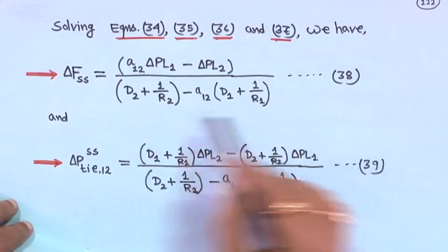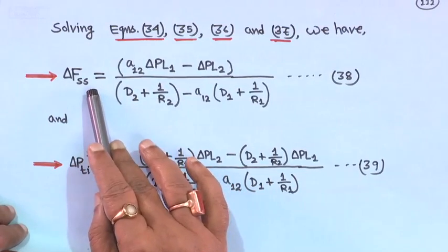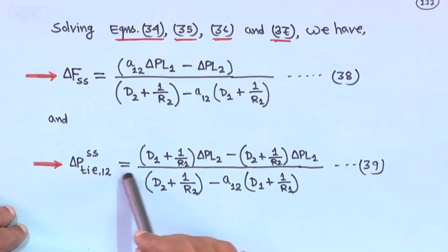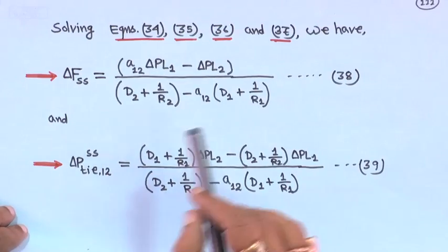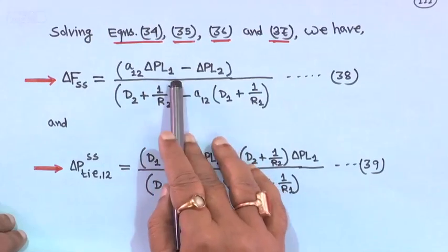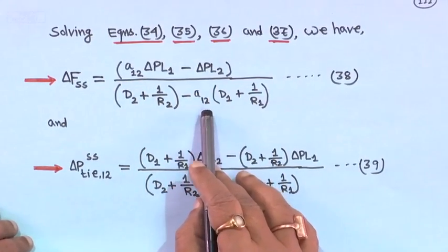Okay, so we have seen the expression for a two-area interconnected system: this is the frequency at steady state, and this is the tie power flowing from 1 to 2, the steady state values. And we have seen one special case when the disturbance was in area 1 and in area 2 it was 0, and the area capacity was the same for both areas.